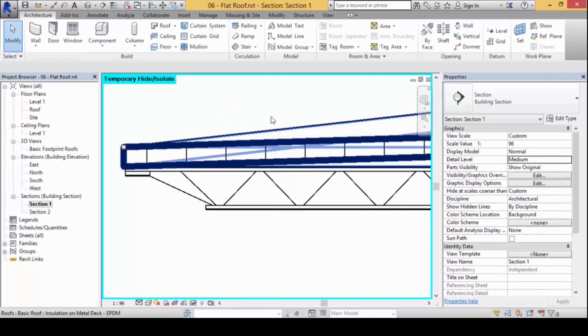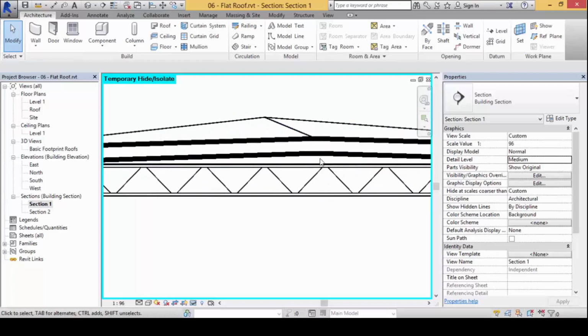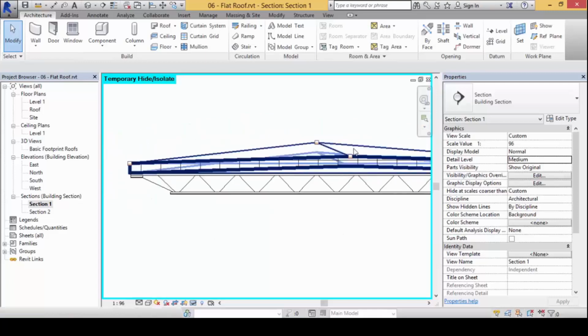It now looks like it is tilted here because we set two different points for the roof to go up and down. It now looks thickened. It's tilted already. You can apply the same principle taught to you here on toilet flooring. If you need it to fall in a particular direction, this is how you do it. You define a point, and that piece of slab is going to drop accordingly. Alright? It is like that.